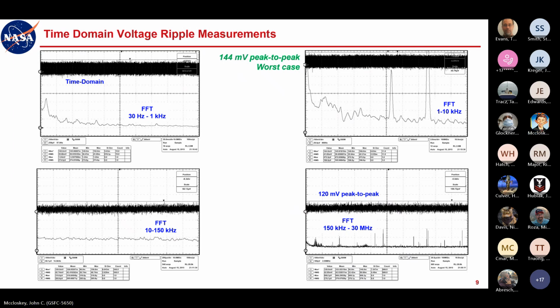But these results were kind of wonderfully bland, just a bunch of white noise. This is with everything powered up and operating in a normal configuration. We did run in a few different frequency ranges, and we used a scope that could take an FFT, so you can do that if you want. That wasn't really required, but it was just something we did with the capabilities we had to get some idea of some of the frequency content.